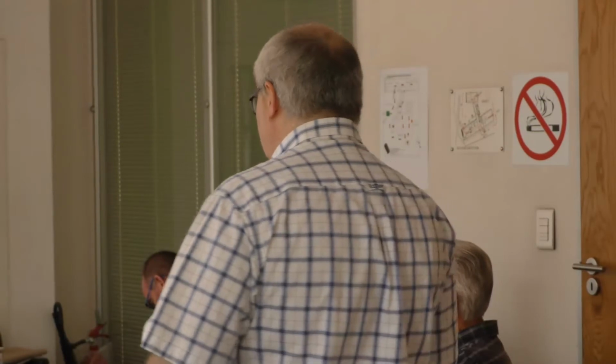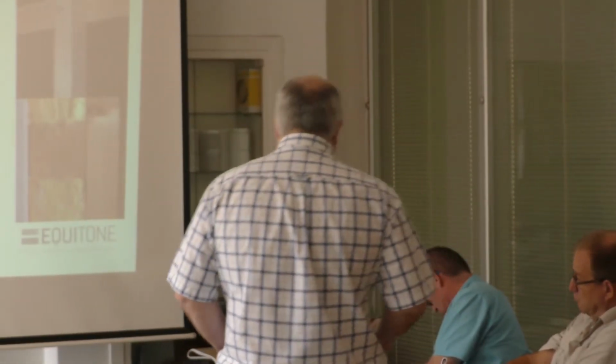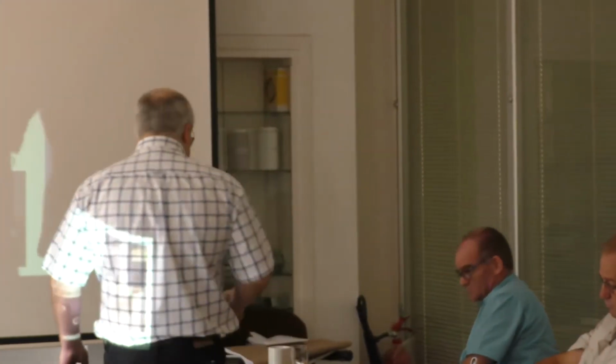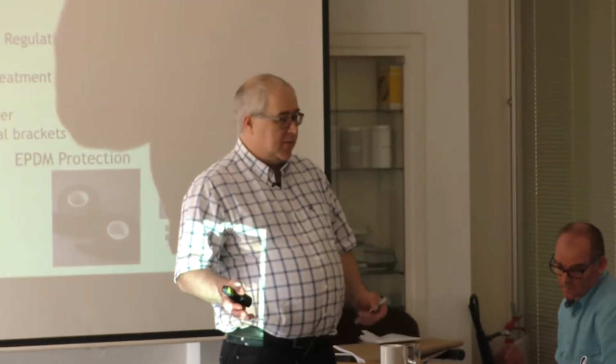We've always protected timber with EPDM strips along the face of it. And you can have systems that are adjustable or systems that are actually fixed in place. Okay? I'll give you an example. In France, where Louis is from, 70% of what we fix is on timber battens.